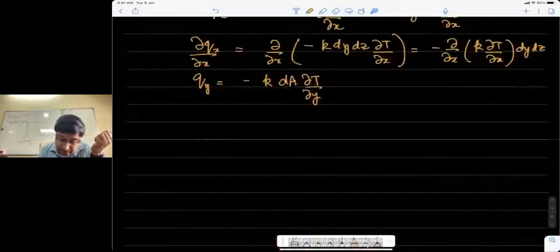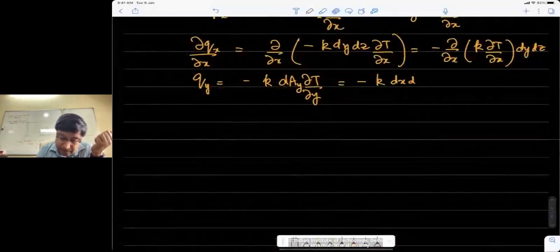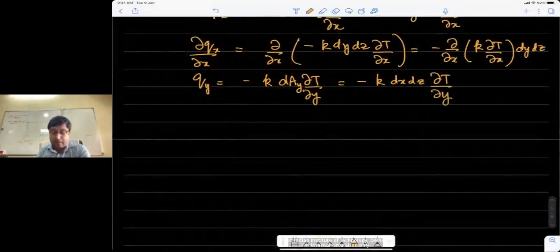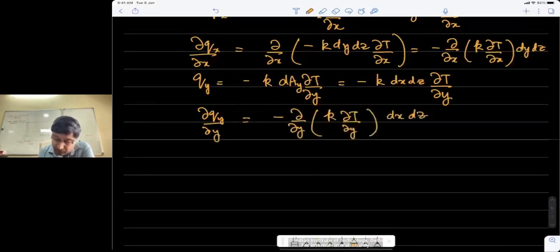So this is minus k dx dz dT/dy. So dqy/dy would be minus d/dy of k dT/dy dx dz.